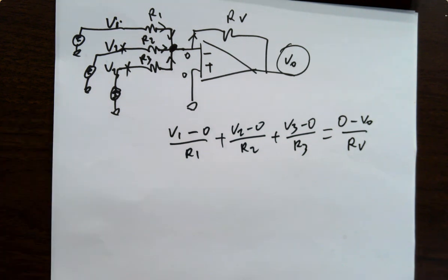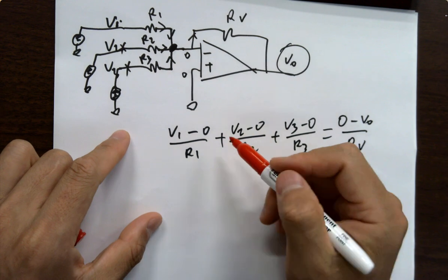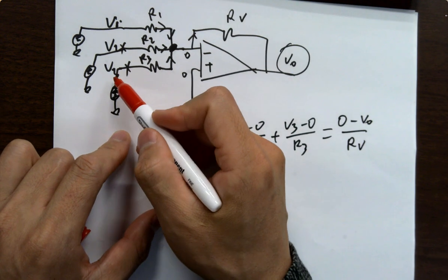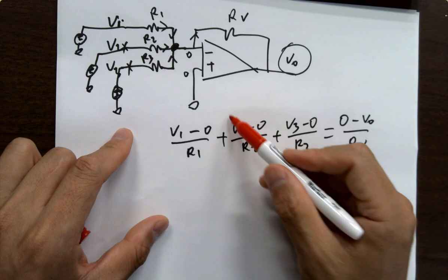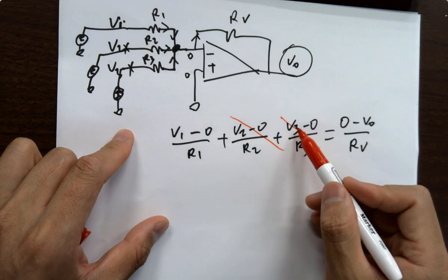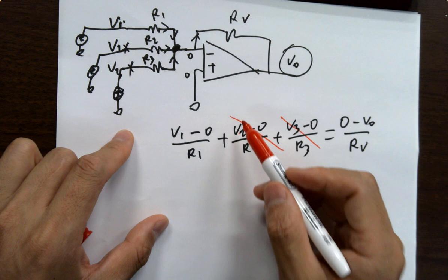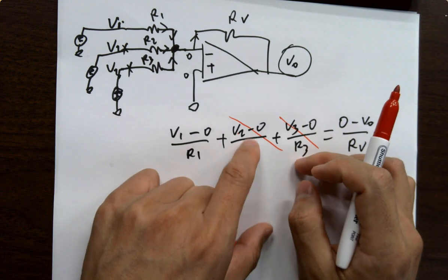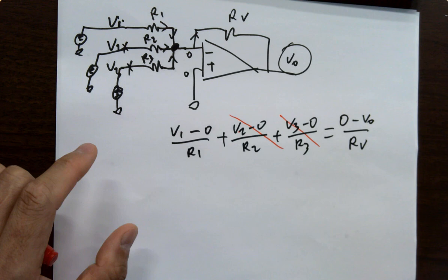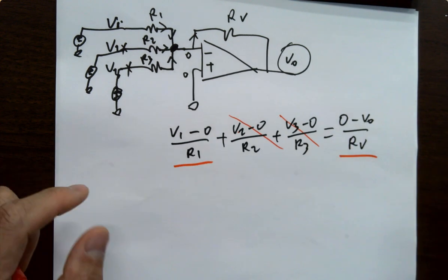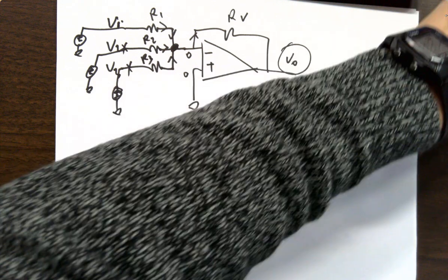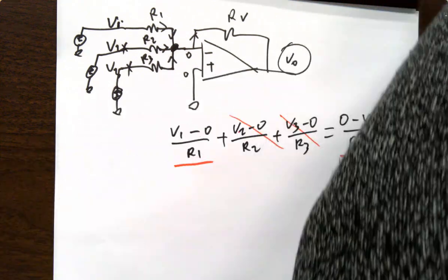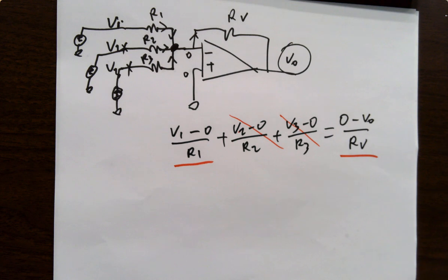If it's asking you to assume that V2 and V3 are off, which means you want to ignore these two or give a 0 to these voltages. You don't even want to use it. Just don't give a 0. Giving a 0 is grounded. Just don't even give anything to it. I think that's the only thing you need to use. All right? Make sense? It's unclear here because it's just telling you it's off. What does that off mean? Grounded or just disconnected? It's going to be different results.